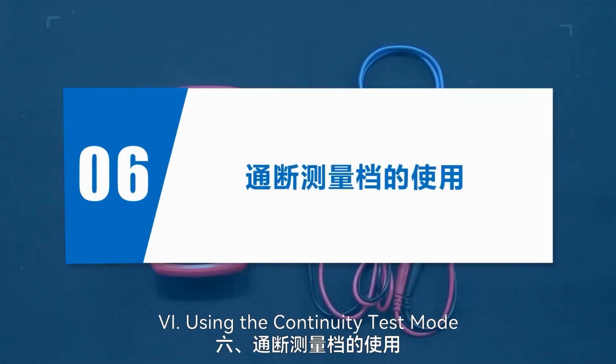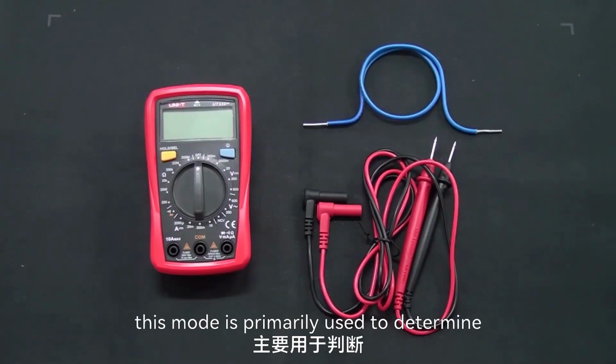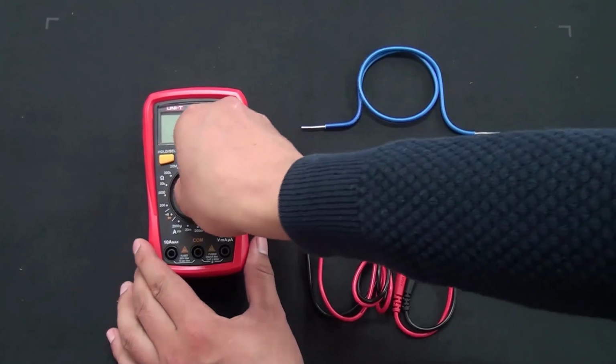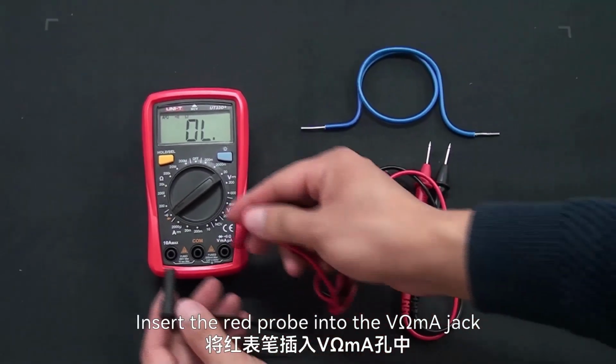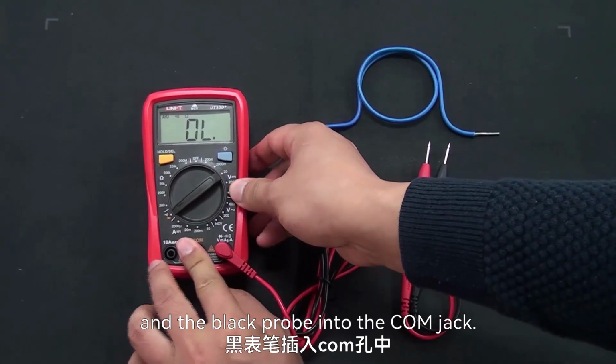6. Using the continuity test mode. In electrical circuits, this mode is primarily used to determine whether a conductor is continuous, intact, or broken. Choose the continuity test mode. Insert the red probe into the volt-ohm milliampere jack and the black probe into the COM jack.